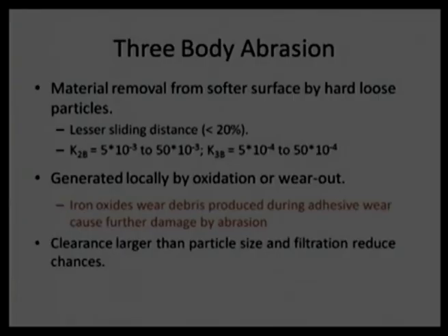Of course, if the shape is very irregular and one dimensional, then sliding will be more. But if the particle has a more spherical shape, if you push it, there will be more and more rolling. So, what we can say, for a loose particle, even though the hardness is very high, there will be overall lesser sliding distance, because there is more rolling distance, and if that is the case, wear rate will be reduced. It will be much lesser. Most of the energy is being absorbed in the rolling action.